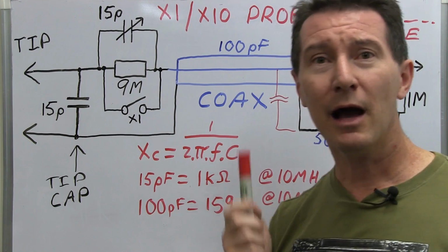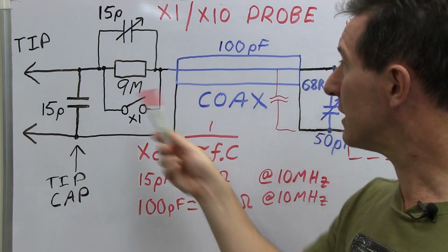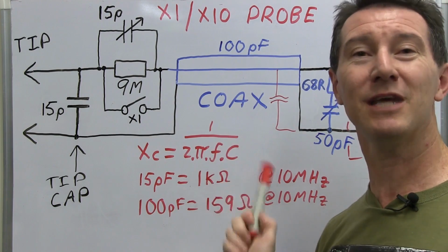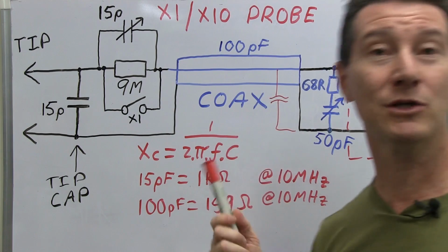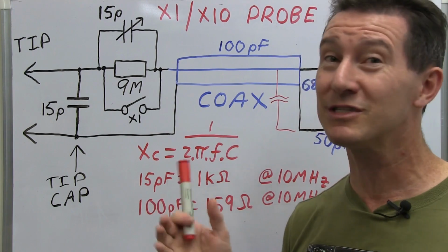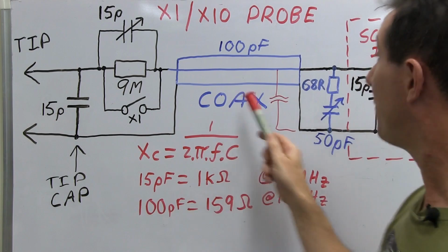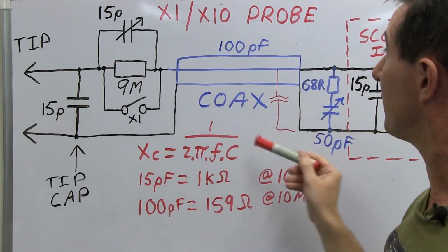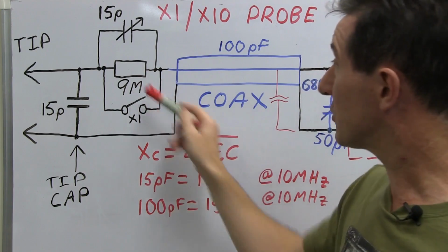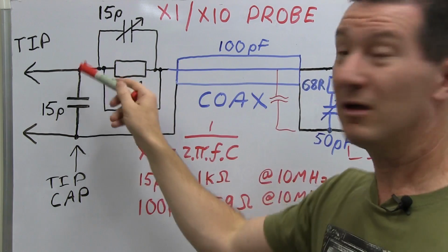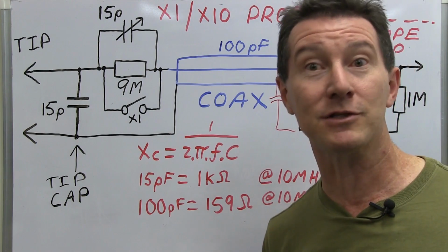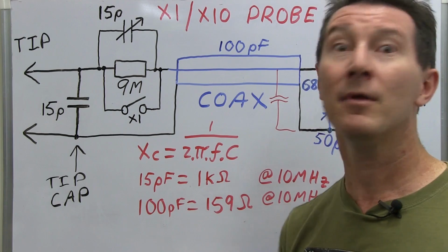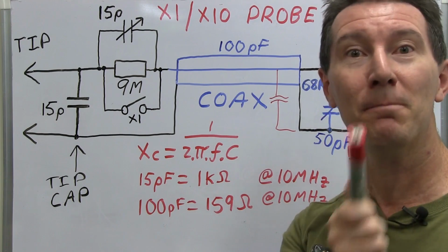So why are we getting that drastic attenuation, about 10 megahertz bandwidth on the ×1 probe, whereas a bit of coax, which is essentially exactly the same thing, it's just, well, let's say it's longer, it's got 115, then effectively, what's the difference between the ×1 probe and a bit of coax? There shouldn't be any difference, but there is. We measured it. Why? I think we can solve this one with a multimeter.